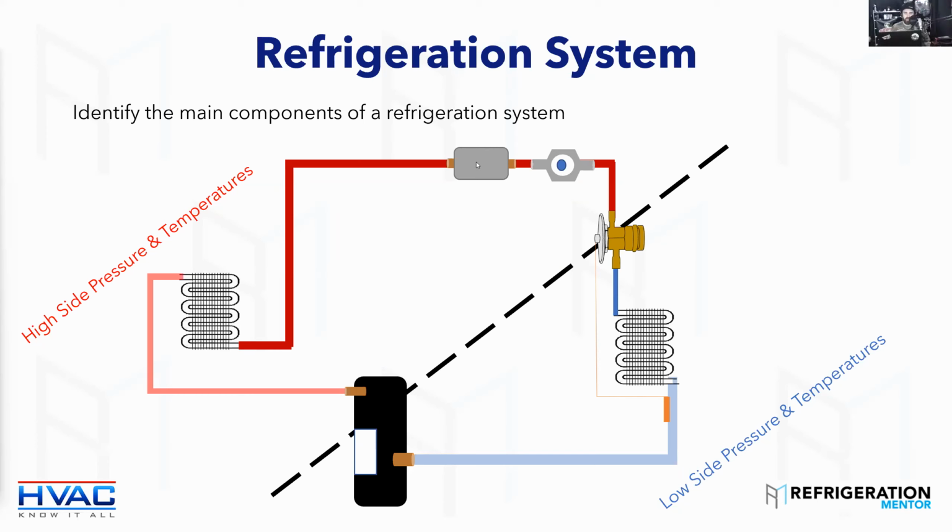You're talking about an internal plug in the condenser. Yeah, inside, not a dirty condenser. Sorry, not a dirty plug. Internal in the piping, and it's flashing the gas. Had that happen just yesterday, Trevor. Had non-condensables in a microchannel condenser 3 stories up from the unit that's in the basement. Wow. Similar symptoms to what you were just saying.